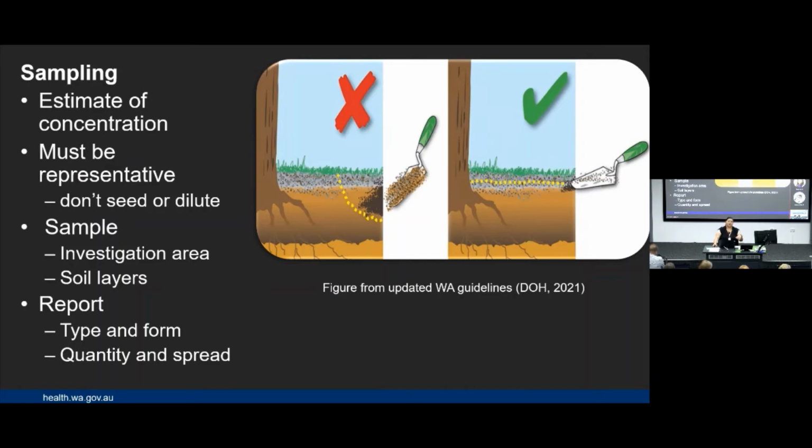and then it also informs your decision of what kind of removal or remediation needs to happen because of the quantity that's there. Okay, so we've selected the Class B or restricted licence removals because of this reason, or the soil contractor with a safe work procedure is picking up any fragments that they find when they do these additional cutting and filling works, and it's all under a safe system of work and they've all been trained and it's all under 10 square metres and we're all compliant with that. So having enough information is important so you can make those subsequent decisions about remediation and management.